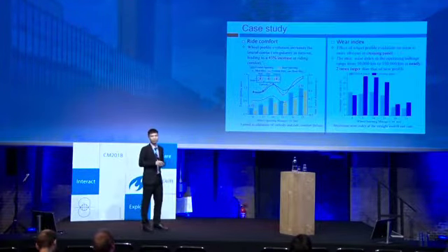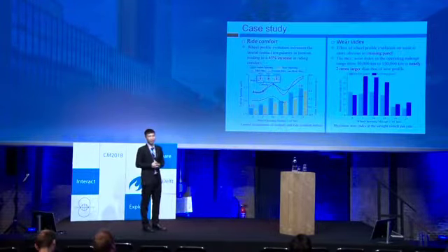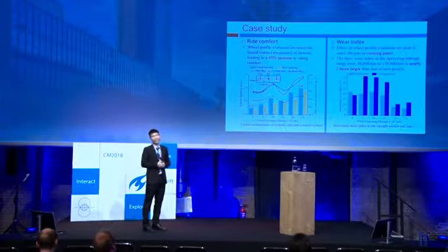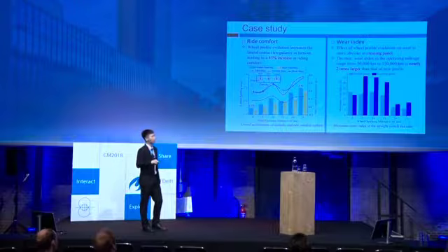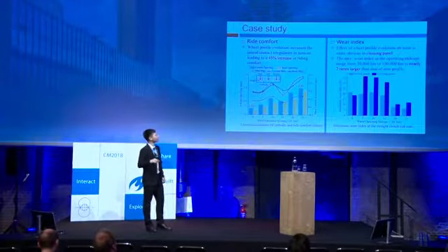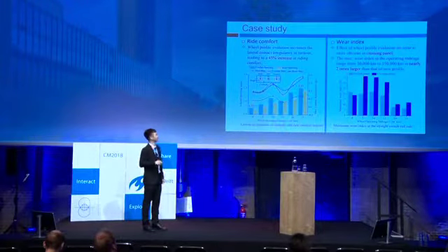As I mentioned before, with the wheel profile evolution, the wheel transition position is shifted backward, and the lateral contact irregularity is enlarged. So the lateral spur index increases from 1.73 to 2.51, by 45%. For the wear index, it is found that with wheel profile evolution, the maximum wear index in the operation mileage range from 50,000 kilometers to 150,000 kilometers is nearly 2 times larger than that of the new wheel profile.